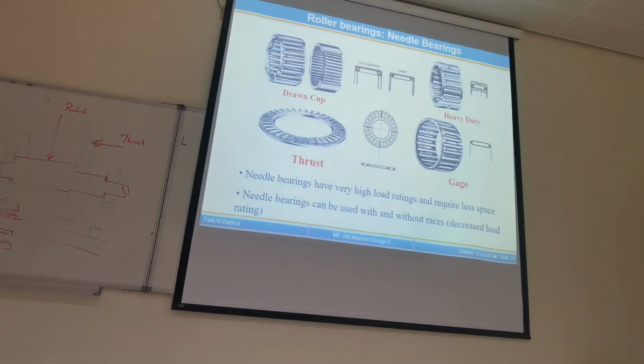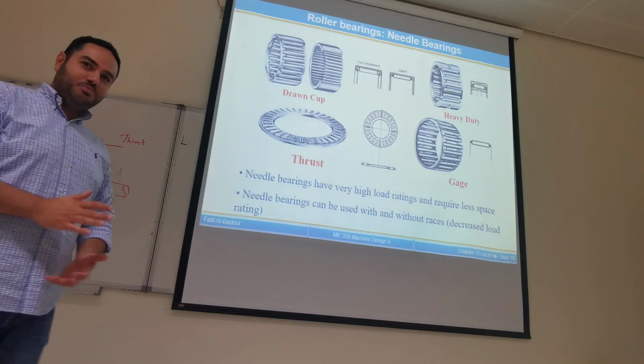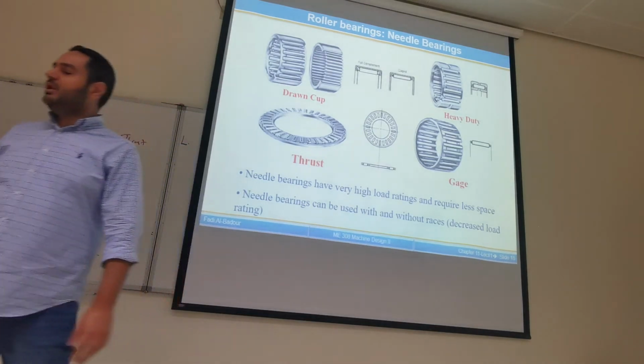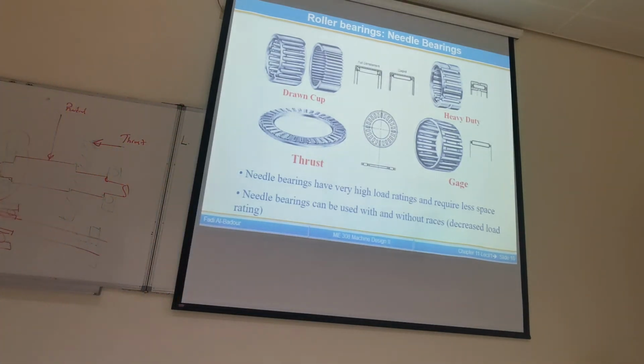Now remember, when we manufacture the roller, if they are made of steel, they are hardened because the roller will carry compressive loads. This is why we call them bearing stresses. Bearing stresses are compressive stress. So the rolling element inside should sustain high compressive load.